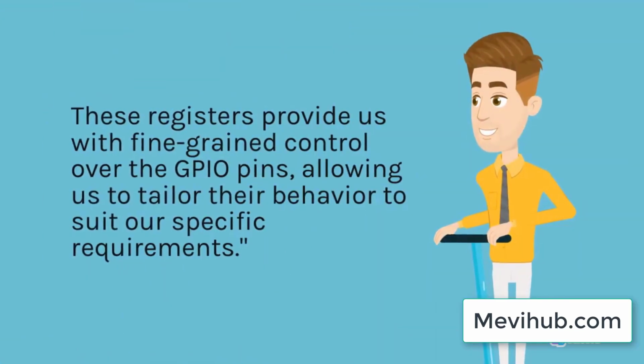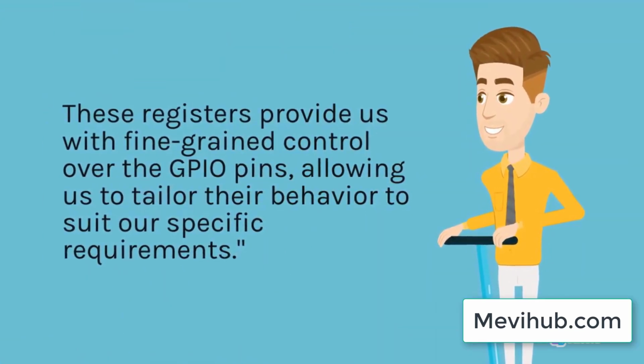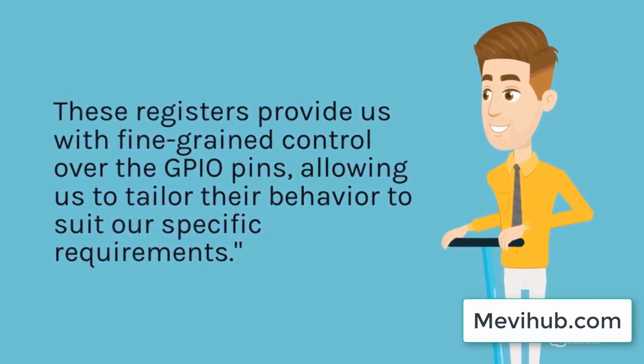These registers provide us with fine-grained control over the GPIO pins, allowing us to tailor their behavior to suit our specific requirements.